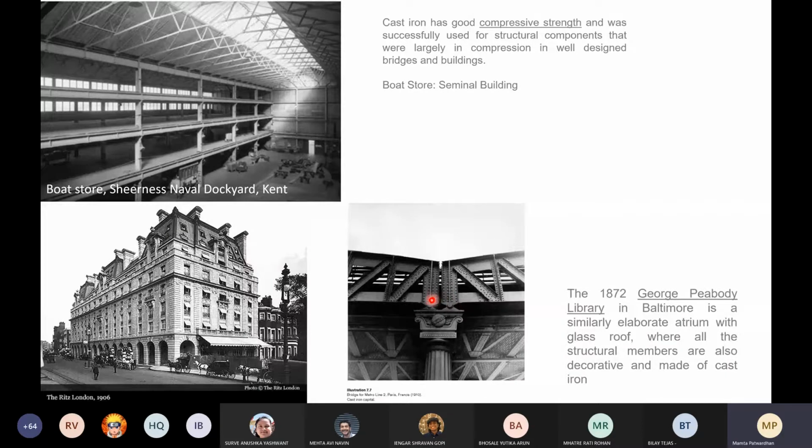Here again we have a cast iron capital. So try and understand that they're still not moving away from the appearance of the column. It's still looking like one of those classical orders. This appearance has not moved away into becoming just an I-beam or a C-section or a built-up C-section or whatever it is. It still looks like one of those classical orders. They've not moved away from that, but they've actually gotten into using this cast iron material. They've gotten into using this built-up truss, where these are all resting on this vertical member. So this is something which you need to keep in mind.